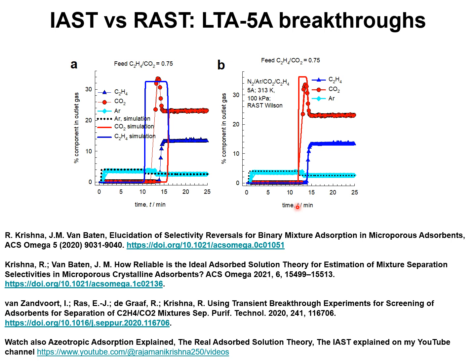However, the experiments reported by von Zandvoort and others, including myself, and reported in Separation and Purification Technology in 2020, show that LTA5A could also be a candidate adsorbent, provided the feed mixtures are significantly leaner in C2H4 with respect to CO2, as is the case in the OCM reactor products.